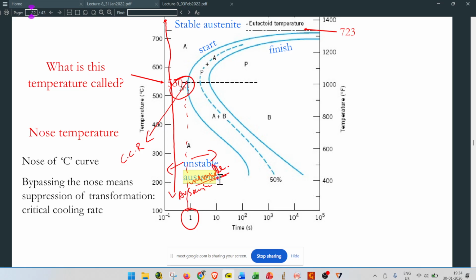It is like a stabilizer; carbon tries to retain the austenitic phase. If it is retaining the austenitic phase, then to convert into the martensitic phase we have to reduce the temperature lower and lower. Sometimes we may cross room temperature to form the martensitic phase. Are you getting what I'm trying to say?